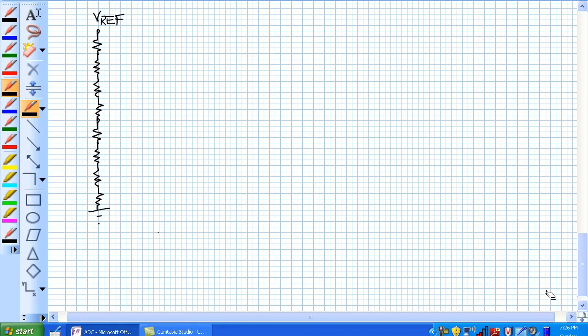And according to the voltage divider rule, if they're 3 identical 5K resistors, they should each have the identical voltage drop across it. Okay, so same thing here for a Flash ADC. Basically, what do we got here? 1, 2, 3, 4, 5, 6, 7, 8 resistors here. And whatever this voltage reference here is, each one of those resistors, if they're identical, should have 1/8 of VREF drop across it. Dig?